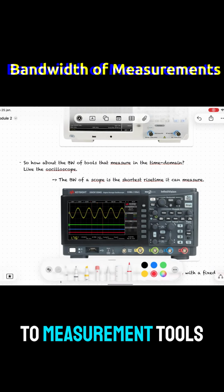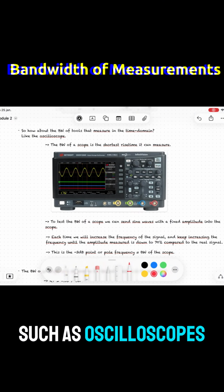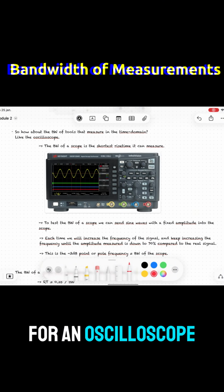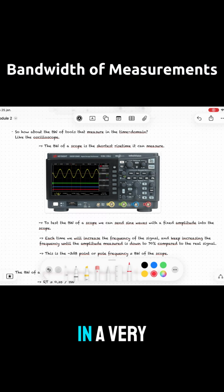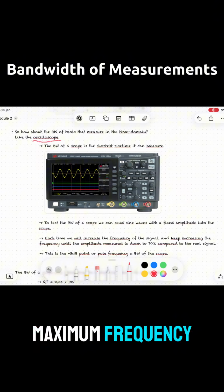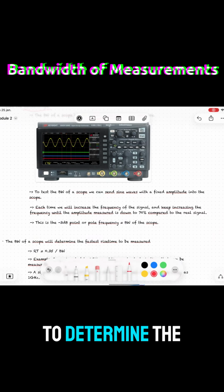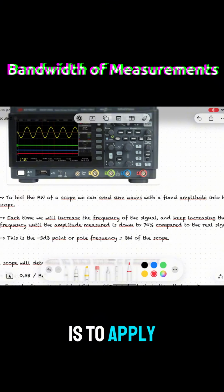Now let's switch to measurement tools that operate in the time domain, such as oscilloscopes. For an oscilloscope, bandwidth is defined in a very different way. Instead of being specified as a maximum frequency, the bandwidth of a scope is tied to the fastest rise time it can accurately measure. One common way to determine the bandwidth of a scope is to apply a sine wave